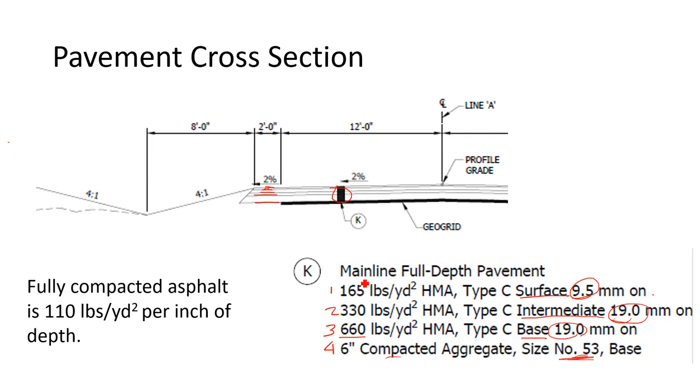Right, and so it can become a pretty dense item, but also without the fines in it, it still drains well, so it makes for a good pavement base. Because in the end, constructability is an issue. You want to have a base that you can drive a whole bunch of dump trucks and the paving machine across as you're putting these other layers on, right? And if you've got too fine of a sand or something, all that equipment is just going to rut it, and it's going to be a mess.